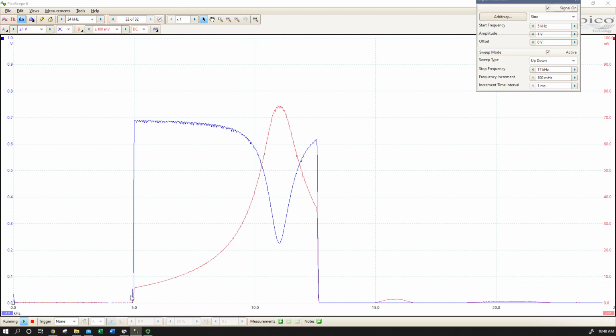So it's basically all a matter of how much data you want to collect. We're going much slower as well. You can see we're moving much slower over our sweep range than we were before. We could get to a nice curve either way. If we sweep faster, collect fewer times per movement increment, we just have to sweep more times. So eventually, one way or another, you have to collect the data you need to get a good resolution to make your measurement. A little measurement theory there.